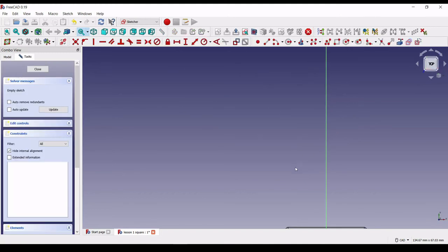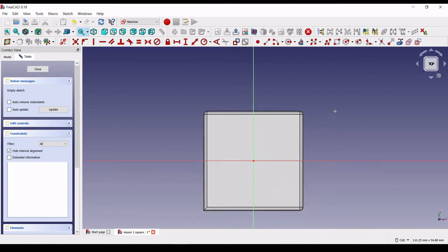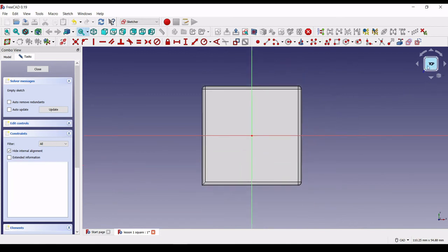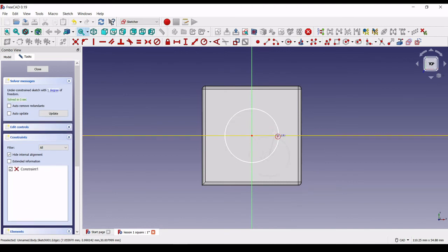But now I cannot see where I am, so I'm just going to bring it back, pan it back, and you must make sure that you are now on the top view. And I am going to draw a circle. You will see my arrow changes into a white cross with 2 smaller arrows. Move the cross onto the centerpiece, click and drag it out from there, and double click. If you don't press escape you will have more, so just press escape to delete that part.